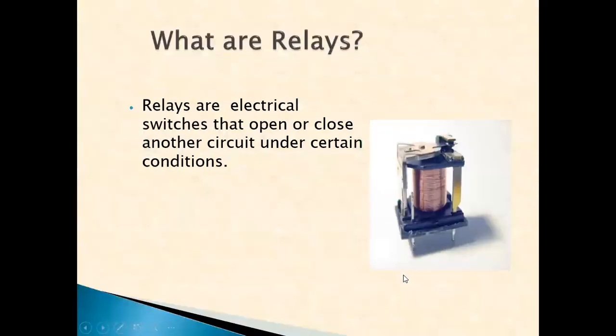Today we are discussing the topic of relays, their terminology and definitions. So first, what are relays? Relays are electrical switches that open or close another circuit under certain conditions. Or it is a device designed to initiate isolation of a power system or operate an indication system on occurrence of a fault.